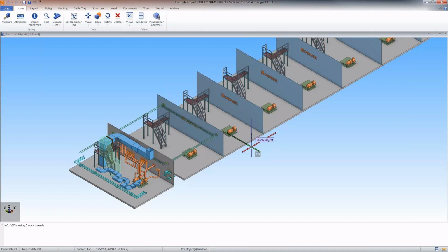So when I toggle 2D and 3D hit with Ctrl 2, the tag changes to reflect that. With the 3D hit, the cursor must be navigated in the object's boundaries to be able to pick it, while with 2D hit, you're selecting the nearest object from your point of view.